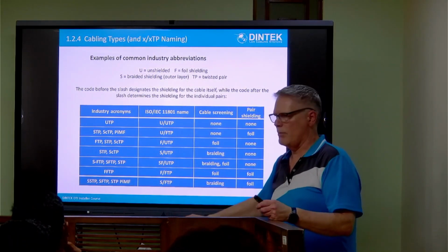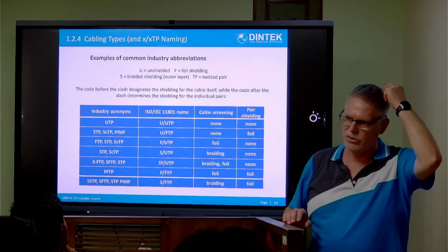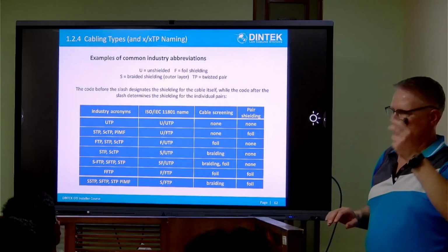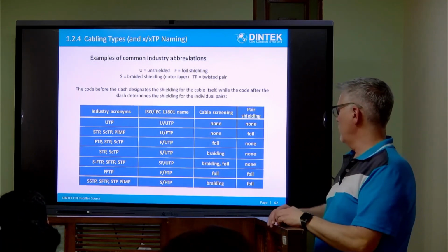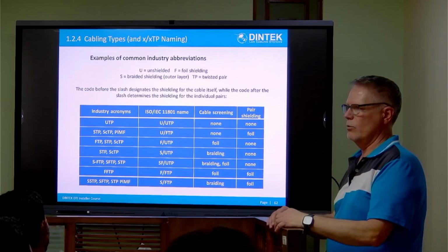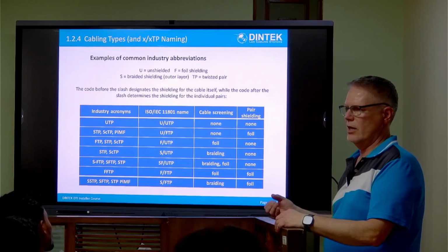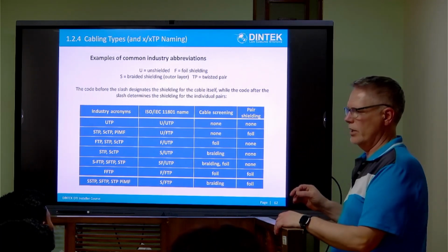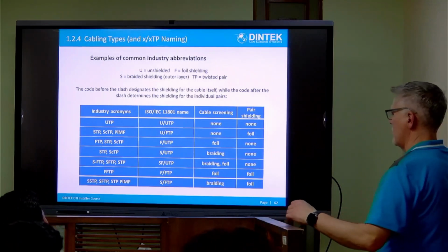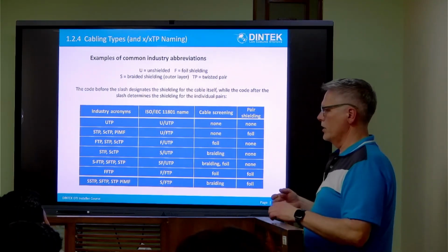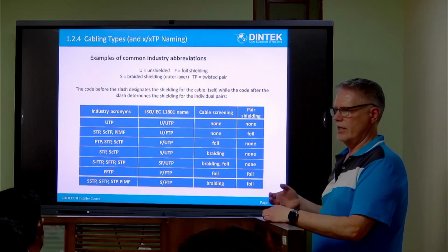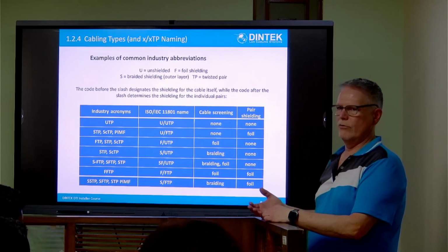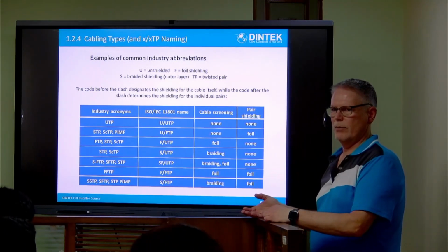The next step up is usually a shielded, foil-wrapped twisted pair cable, and predominantly they would always be shielded for twisted pair cable. If you want the best type of noise limiting in, say, a Cat 6A cable, you'd probably go for a shielded four-pair twisted pair cable.